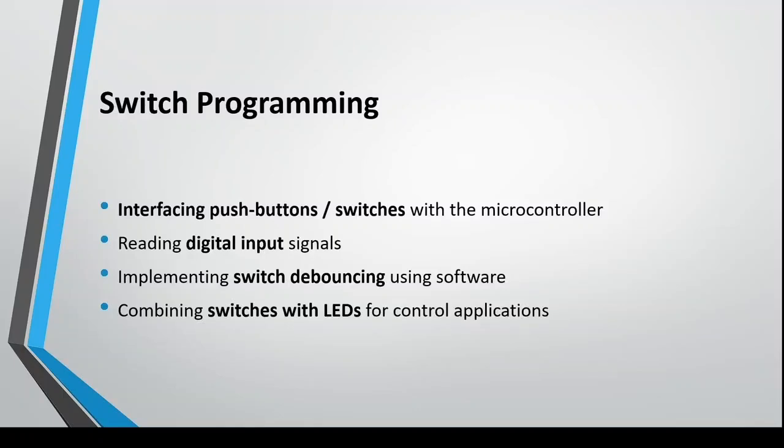Switch programming. I also learned how to interface push buttons or switches. Switches are connected to input pins and the microcontroller reads their state as high or low. I learned about switch debouncing, which prevents false triggering due to mechanical noise. The concept is important for reliable user input.